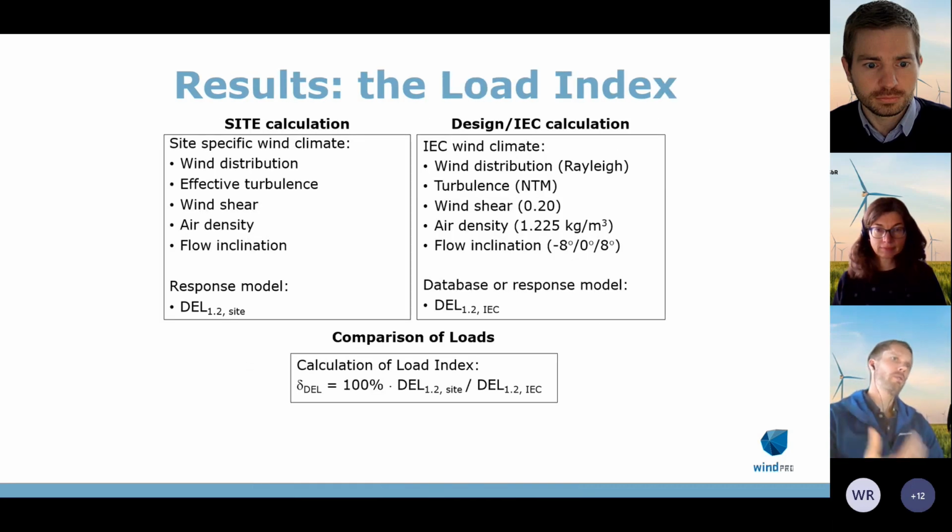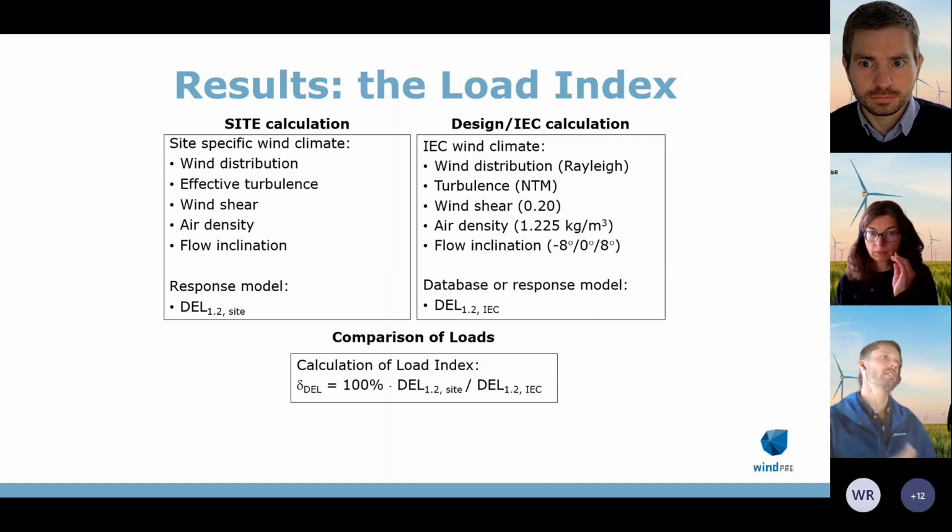So when we talk about loads, you could say a main result is what we call the load index. I want to just describe to you what this is. Basically, it is when we take this response surface method and we calculate loads for a site climate. So that is, you could say, the result of a site compliance calculation. You get what we call a damage equivalent load, a DEL. In this case, I focus here on the design load case 1-2.